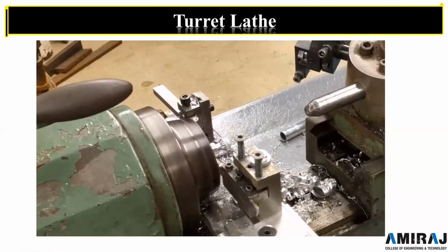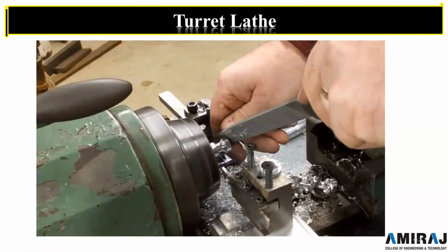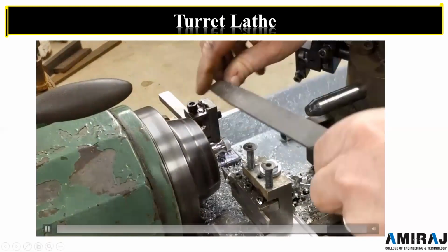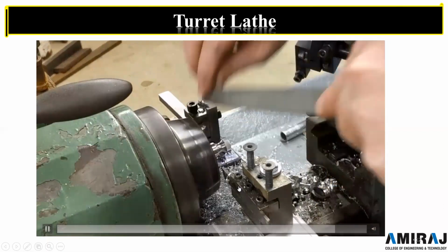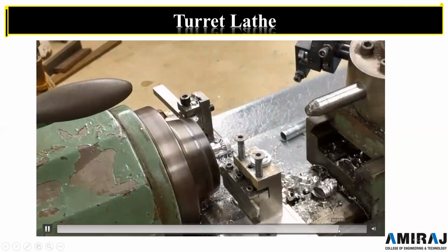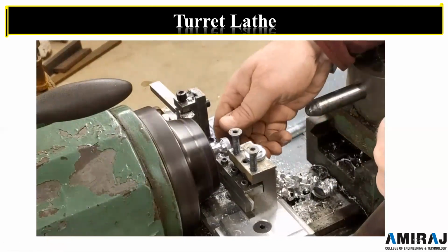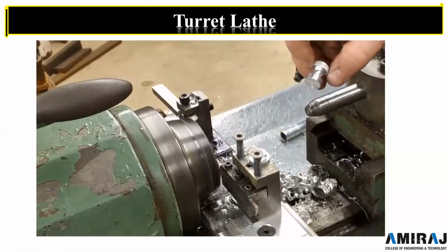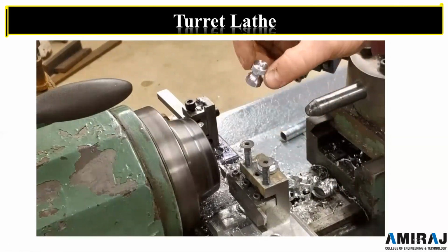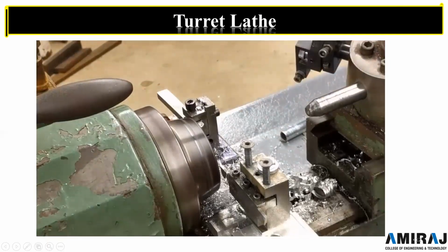And this is the parting tool also. The parting tool can be used to part off the workpiece, or to provide a deep groove. You can see how the part is cut with the help of the parting tool. So this is how the turret lathe machine is used to do multiple operations.